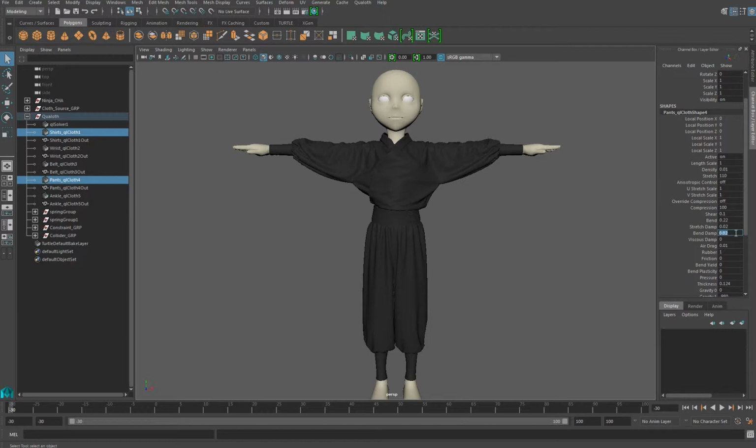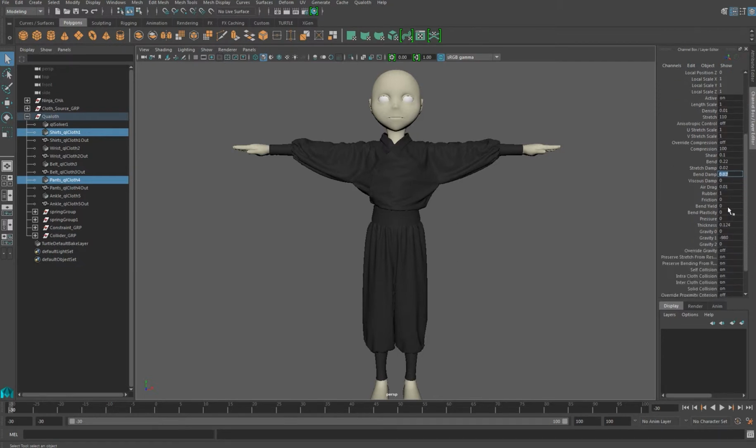We can put more details on stiff cloth with thickness. To get the uniform's feeling that doesn't recover from its actual shape, put 20 in bend yield, so it can maintain current wrinkles and folds. Put 0.4 for bend plasticity, so it gives more strength value of wrinkles and stiffness. Now you should have the cloth that moves with a stiff feeling.